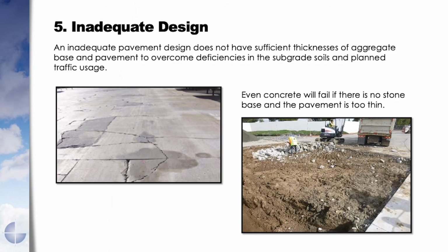Number 5, inadequate design. Usually when we talk about adequate design, it comes down to pavement thickness. This truck area on the left is concrete that we were brought in on. This is a concrete pavement that's between 5 and 8 years old. Unlike the example I showed you with the poor base, it's cracked, but the slabs aren't rocking. They're not settling like where the slabs had collapsed under the poor drainage.